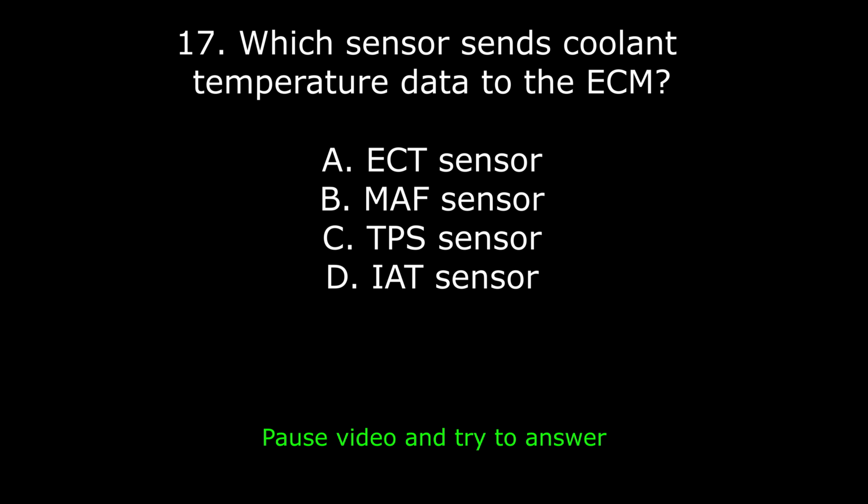39. Why must refrigerant recovery be performed before system service? A. To prevent oil contamination. B. To reduce system weight. C. To comply with EPA laws and prevent atmospheric release. D. Decrease pressure. Answer: C. Comply with EPA laws and prevent atmospheric release. Recovery prevents illegal venting and protects the environment.